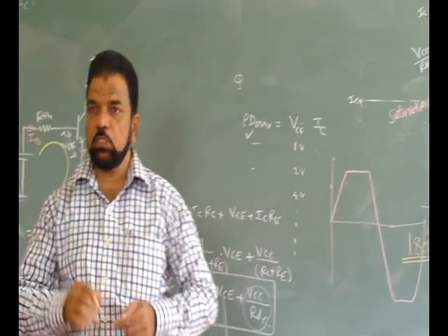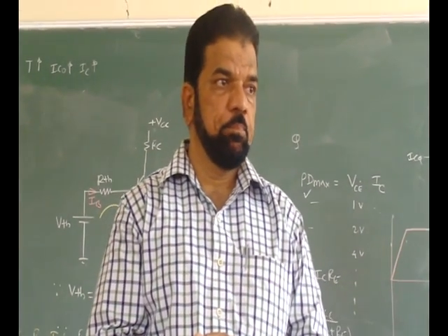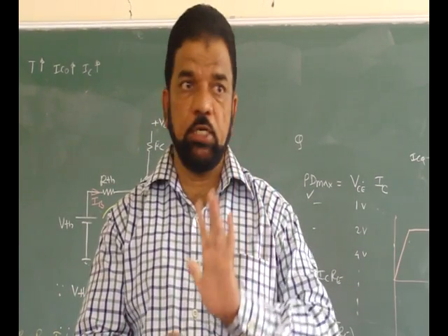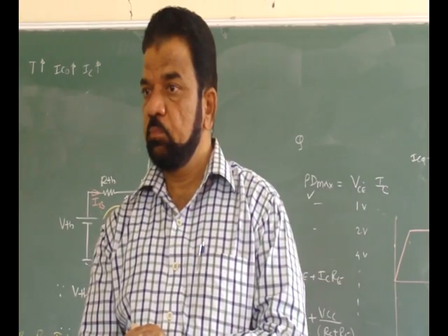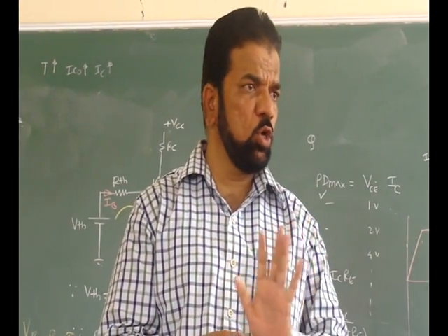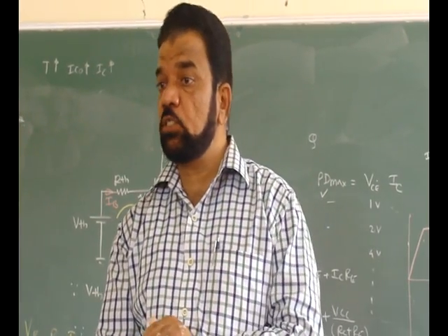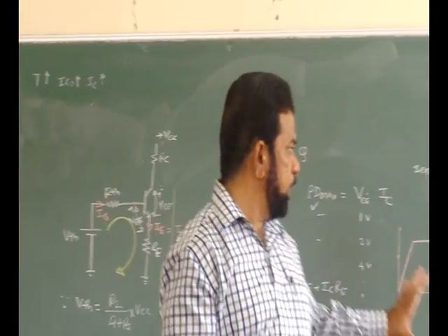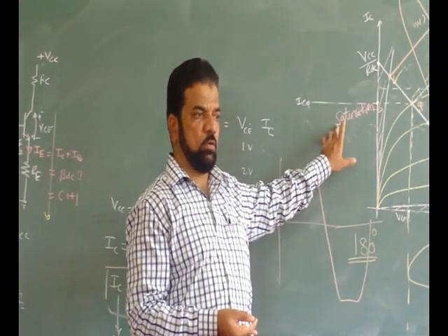It is just towards the square wave. And immediately your reaction is, you have not done it, you have not got the appropriate result, something is wrong. But nothing is wrong there. The only thing is, you have to reduce the amplitude of that function, the amplitude of the sine wave only. Are you getting this one? Once you get the square wave or a waveform like this one, that means your experiment is okay.